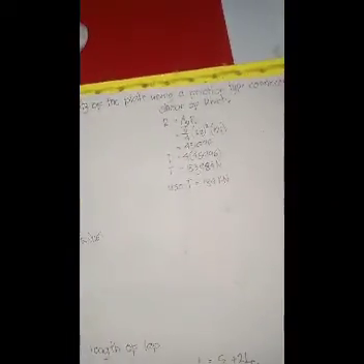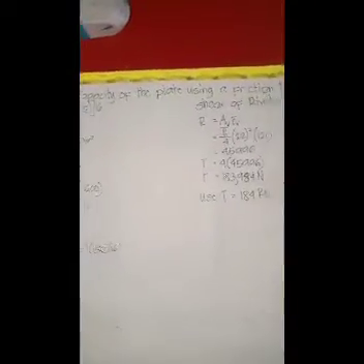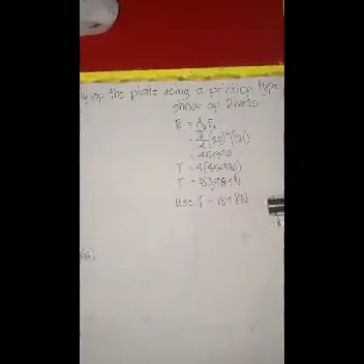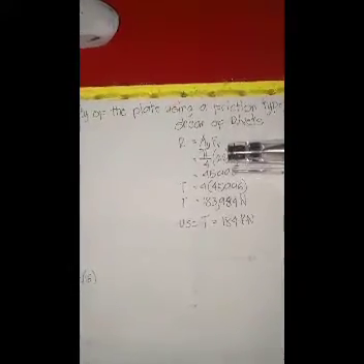Then this is the same as in number 1 for the answer. The difference is that here we use the friction in shear of rivets to get the maximum tensile capacity. Shear of rivets is equal to R equals A sub v times F sub v.